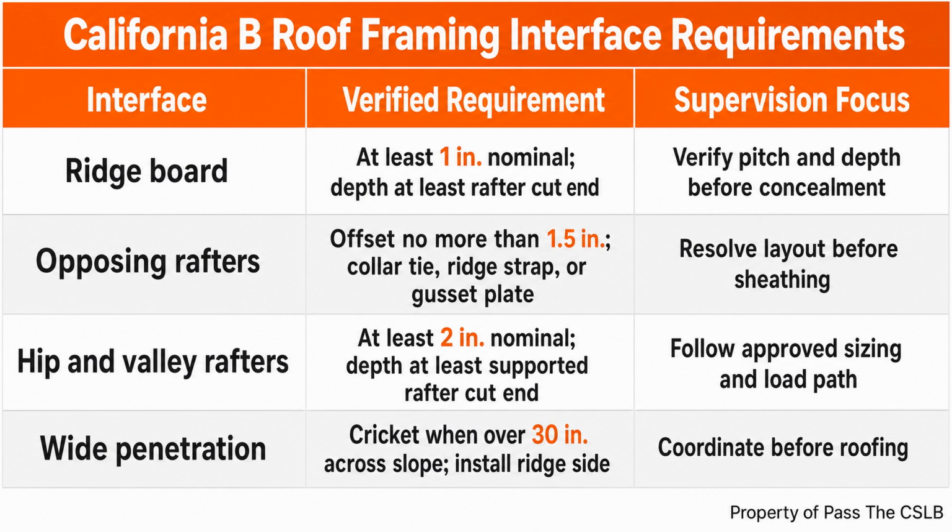Consider a hypothetical family room addition at 2 and 1/2 and 12. The roofing crew arrives with asphalt shingles and plans a standard single-layer underlayment. The shingles are above their absolute minimum slope, but the underlayment method is wrong for that pitch range. I stop the installation before the roof is loaded with material, verify the specified assembly, and require the double application sequence.